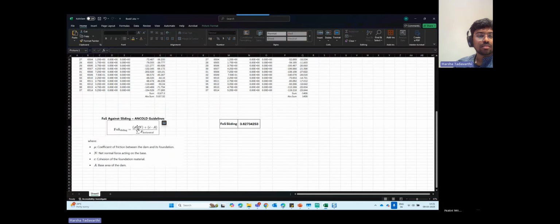So that's the idea. In this case, your dam is safe for SLS condition against sliding, as the factor of safety is greater than 1, which we have it like around 1.44. So hence we can calculate the factor of safeties against sliding. We can calculate the principal stresses. We can see the displacements and so on. And that's the idea I wanted to give with training.